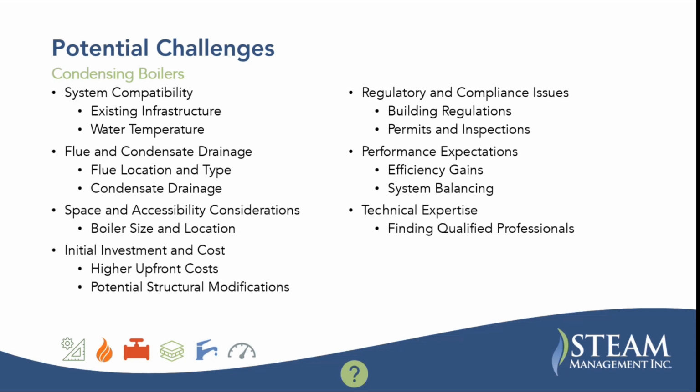These are usually packaged units. They're not field assembled units, so there are space and accessibility considerations. They may have a higher upfront cost and potential structural modifications, especially if you're, say, replacing one boiler with several boilers, or if you need structural modifications to get the boiler into the space.